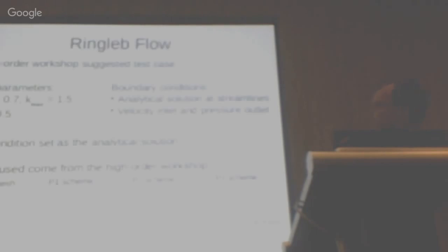So this is sort of a requirement for this kind of solution. And now for this result set here, one of the objectives was to have a high order solver and to know if we are actually getting high order. I consider here the Ringleb flow problem, one with an analytical solution, so I can compute the error related to my numerical one and compute the order of the method.